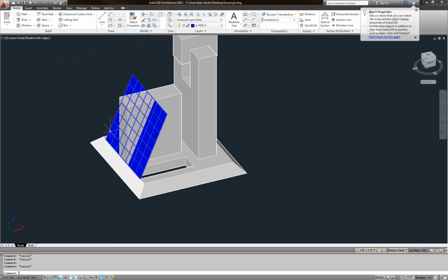So now I could use the slice command, so slice, enter, slice, click on the object. Now it's asking to select the object to slice. Then I'm going to click here, 1 point, 2 point, 3 point, enter. Hold on, slice, select the object to slice, that guy. Select the starting point plane, 1 point, second point, third point, enter.